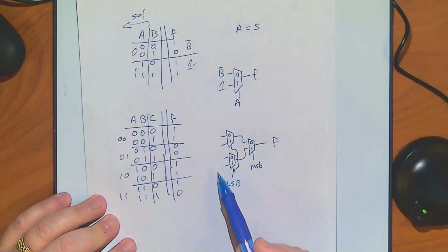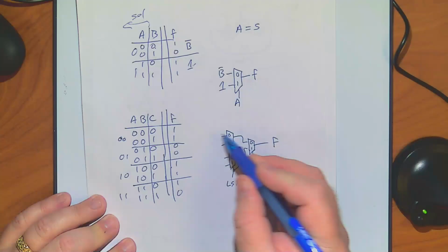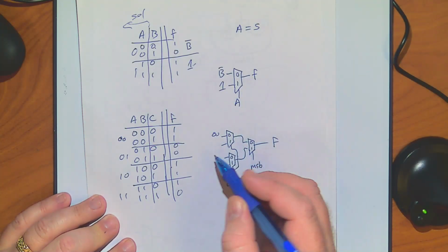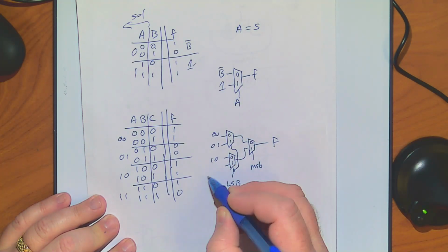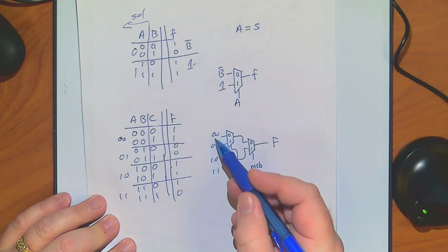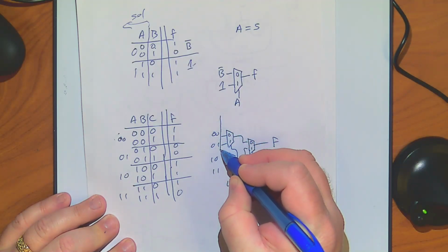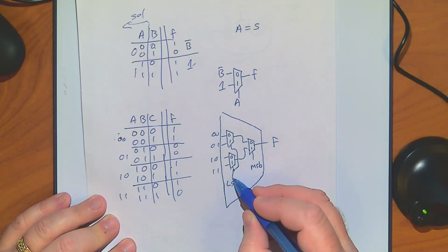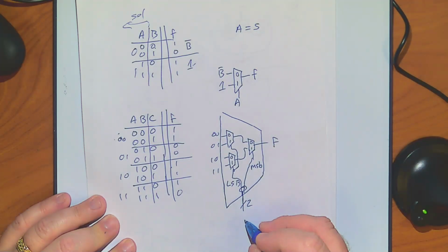So on and so forth. So this is the least significant bit, the most significant bit. And so I have the input: 0 0, 0 1, 1 0, and 1 1. That's the address here, and I want to just hook up whatever the function is there to get the output. So this becomes, in essence, a symbol for a much bigger gate, where these 2 bits just come out. We'll just group them together into a 2-bit address.